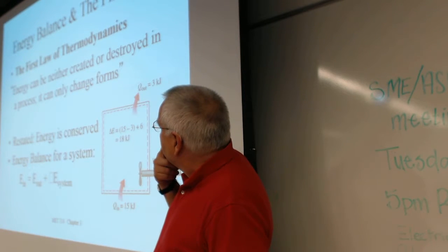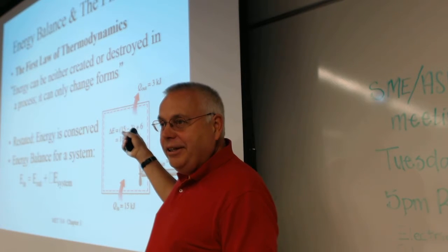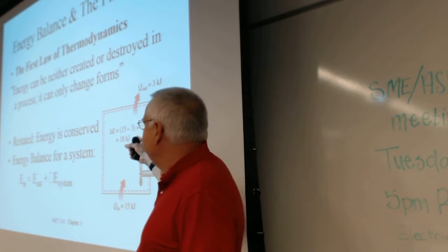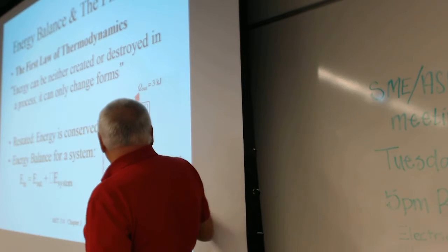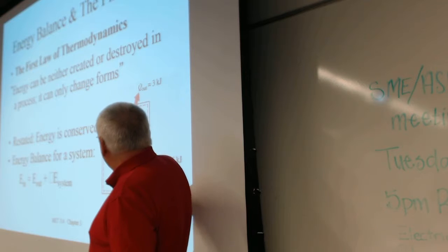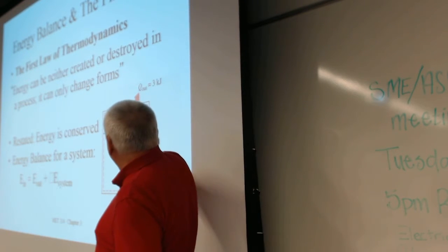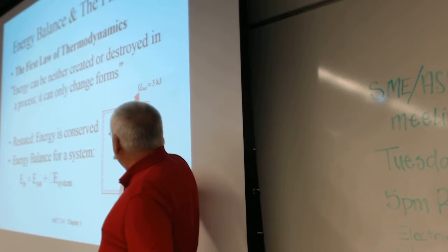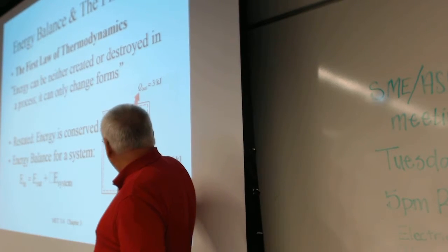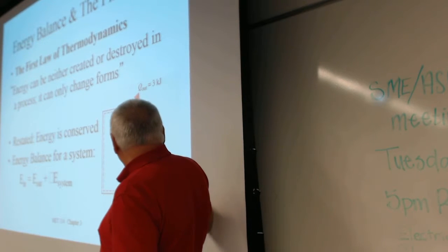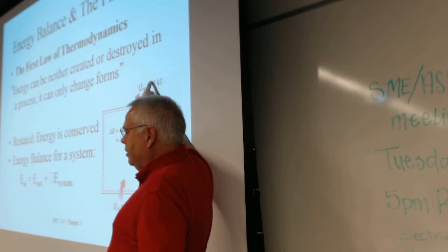So that was a little off topic. Energy balance. So we're keeping track of things. If energy comes in and energy goes out and we do some work, then if we did more work and put in more energy than is coming out, that means the change in energy in this one, for example, we heated it up with 15 kilojoules, we stirred it up with 6 kilojoules, and 3 kilojoules leaked out through the insulation.